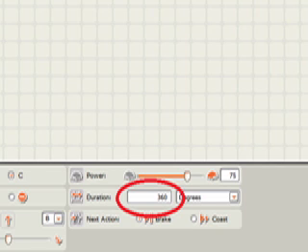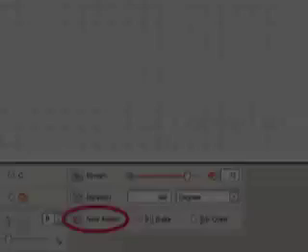If you're calculating how much you want the robot to turn, very carefully turn just one wheel until the robot has turned the amount you need it to. As for which wheel to turn, the right wheel if you want the robot to turn left and vice versa. Again, plug this number of degrees in.